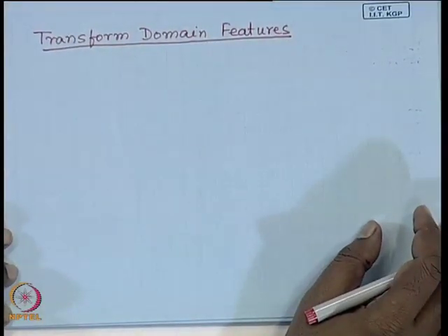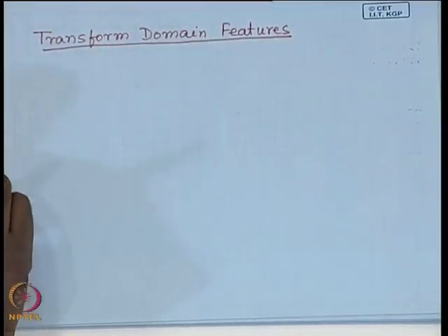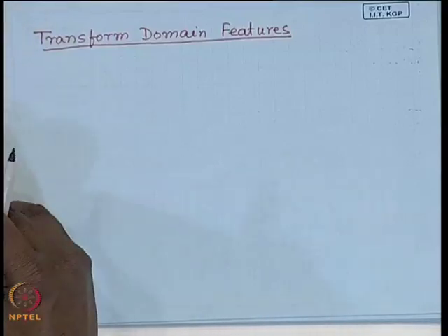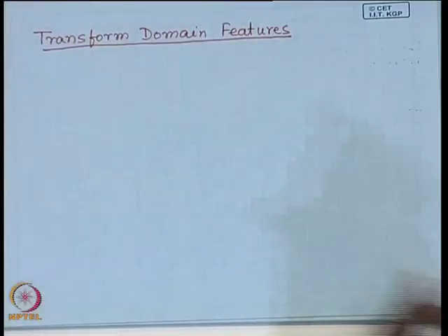Okay. So, whenever we talk about transformation, the first kind of transformation that comes to mind is the Fourier transformation or the cosine transformation. The difference between them is that Fourier transformation gives you complex coefficients, so you also have phase information embedded in the Fourier coefficients. The discrete cosine transformation gives you real coefficients, so you lose the phase information. However, both are very popular in signal processing.